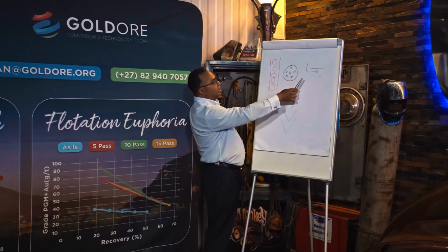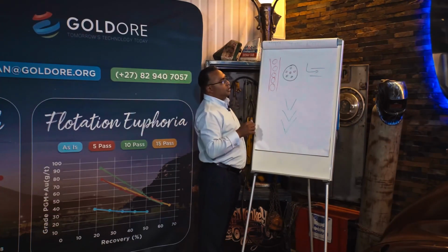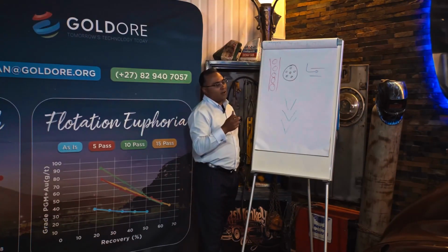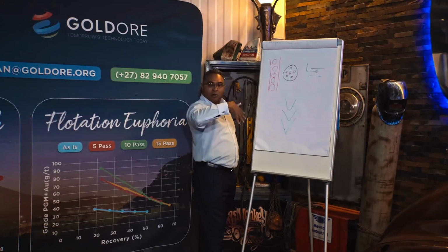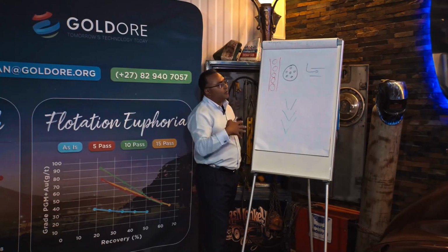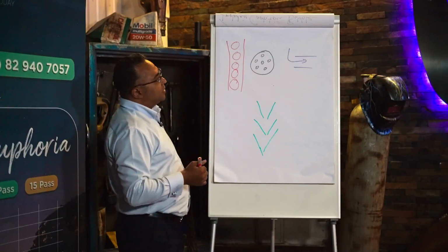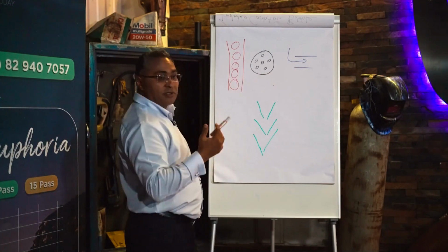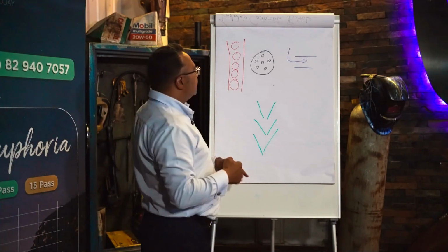And then you get, let's call it, the static mixer type units that, on the one hand, have an orifice plate design, where they have sections of pipe with orifice plates in them to create a bit of a baffle, a bit of mixing as you're pumping through it. So that has a slightly higher degree of efficiency than a lance because there is more mixing and you can shear those bubbles down into smaller sizes.